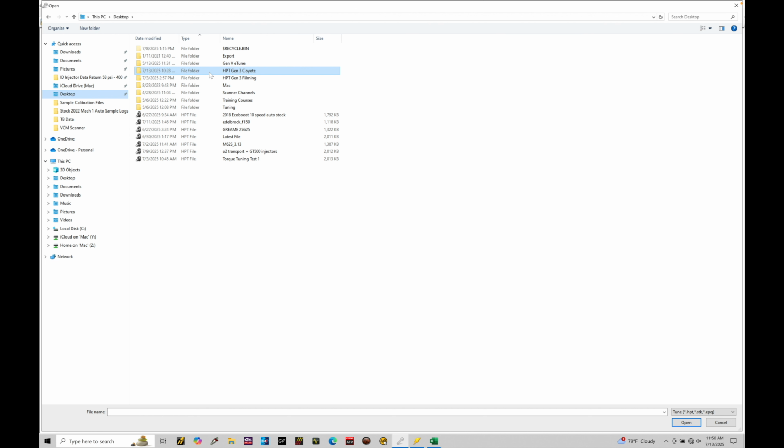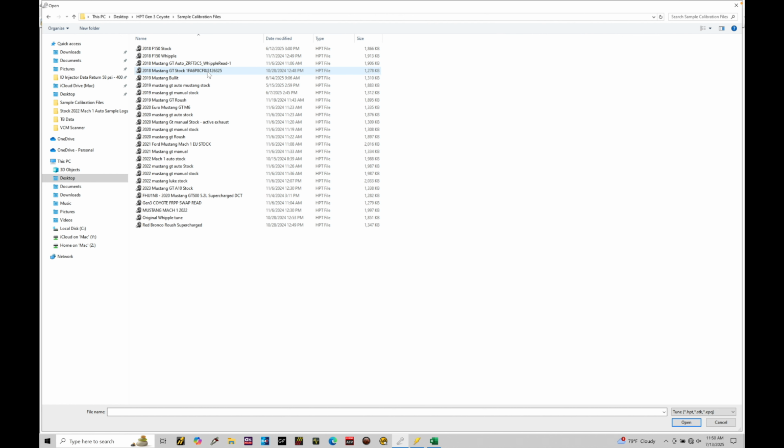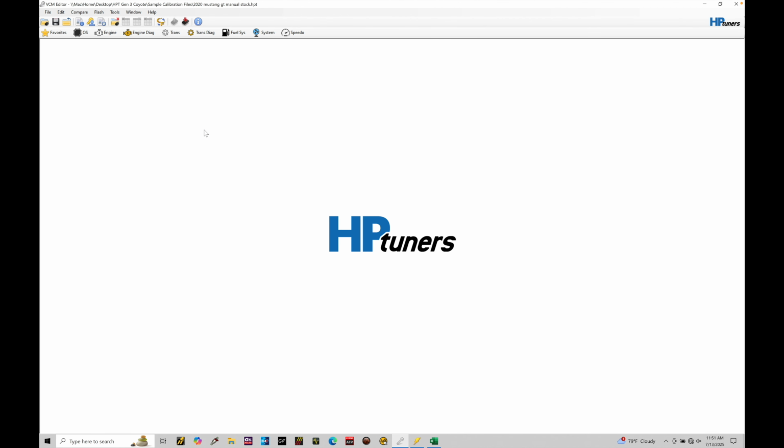Let's go here to our HPT Gen 3 Coyote course folder, and we're going to move into our sample calibration file subfolder. In here, I have a compilation of a ton of different files for stock vehicles, for Roush, and Whipple-based kits. So a lot of good data in here I've pulled and saved while developing this course and along the last few years of doing all this. We want to go in here and be able to reference things. I want to open up a stock equivalent file for the tutorial. Let's just open up 2020 Mustang GT manual stock. We'll use that as the reference point.